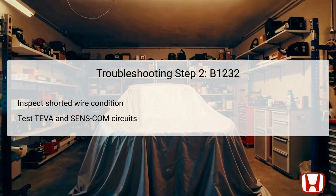Technicians will use a multimeter to measure resistance and check for continuity, ensuring there is no unintended connection or shorting of wires throughout the circuit. If the circuit shows a short, it must be repaired to restore proper function. The test for the TEVA and SenseCom circuits is essential in isolating the issue and ensuring accurate data transmission to the climate control system.